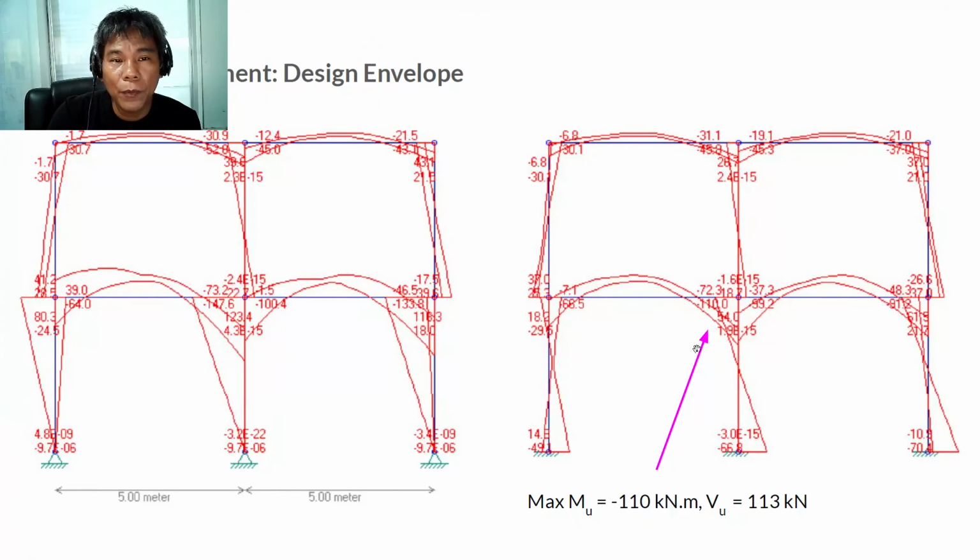and then you can combine these loads to give you the maximum effect. Normally we use the design envelope, meaning you draw all the shear and moment diagrams due to different loads, and you will see the maximum. The design envelope is the boundary of the minimum and maximum values. Here is the design envelope for this structure.